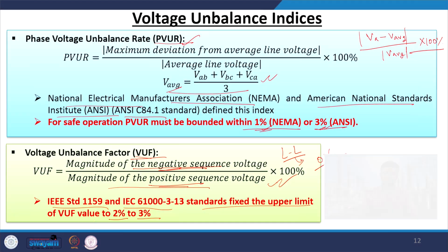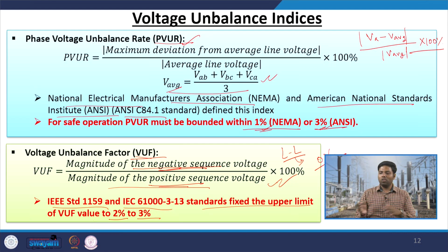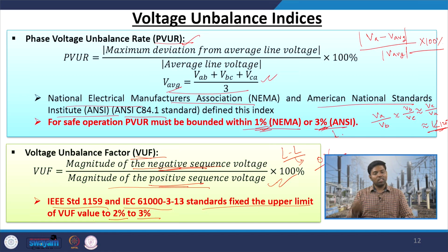So whatever conditions or approximations we took before, that the voltages are close in proximity, with the angle close to 120 degrees, only the phase difference is there and that is also 120 degrees, that is quite true, because 3% is the maximum deviation. So it is around 1% or 2%. If we go with ANSI NEMA, then it will be lesser than 1%. So you can tell that though we have an unbalanced system, still it is running in the proximity of a balanced system.